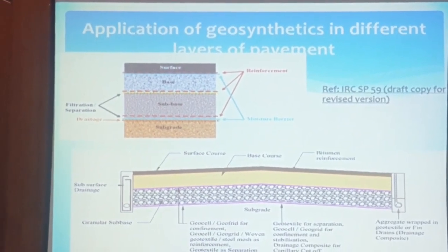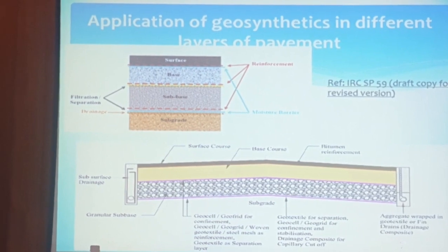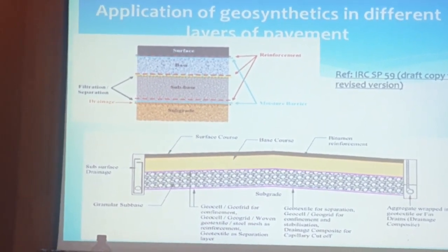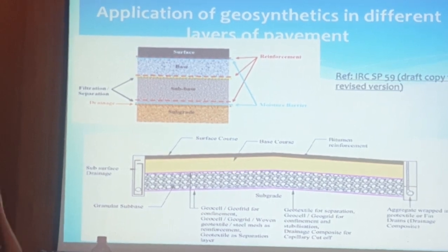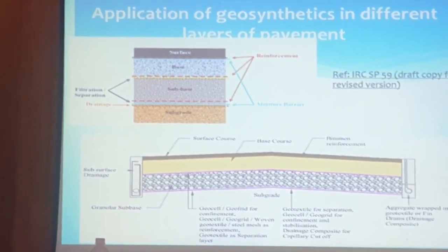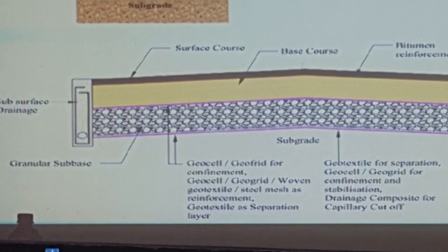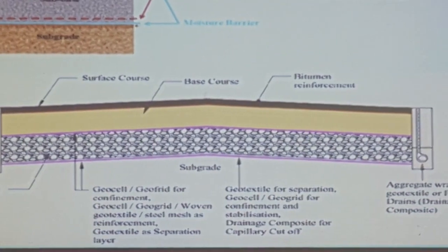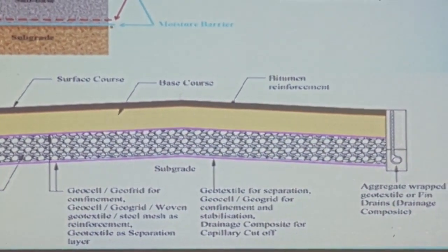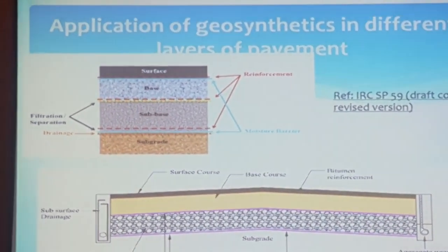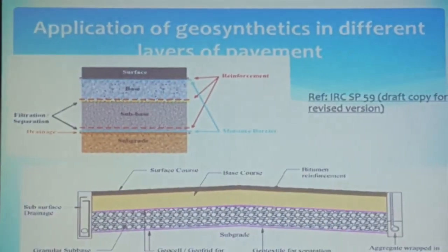If you apply it in the subgrade, suppose your MR value of the subgrade is, say, 100, some factor is there, obviously more than 1.8 or something like that. It will be 180%. So that way it works. It is indirect as per our code, but directly it can also be correlated.